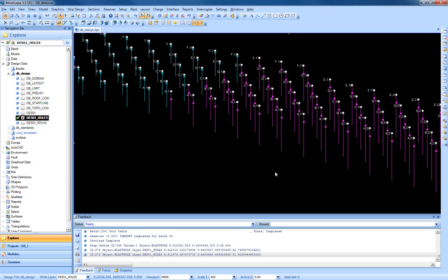Okay. Now we need to move ahead and get the blast holes ready for charging. Before powder factors can be assigned, areas of influence need to be calculated. I will let MineScape calculate the areas of influence. Then I will edit and/or update areas where I think there's too much blast hole influence. So I'm just going to use a collar area because my blast holes are vertical. If I had inclined dipping blast holes, I would use collar areas and toe areas. This way I would get an average.